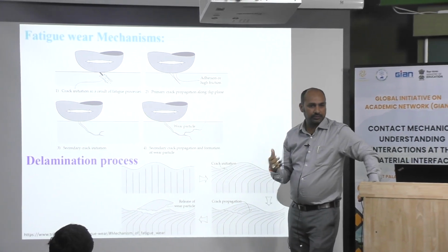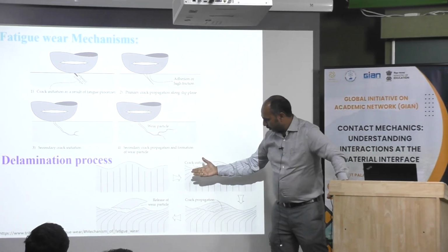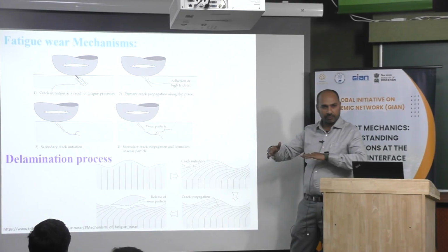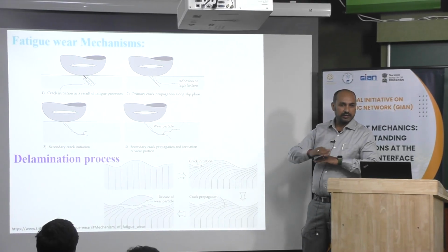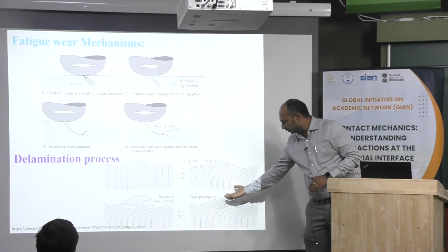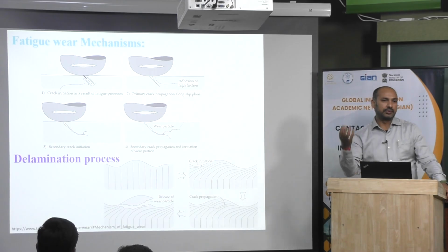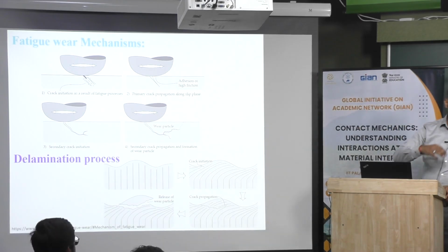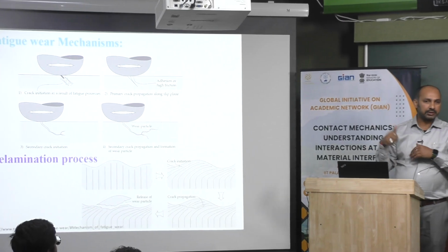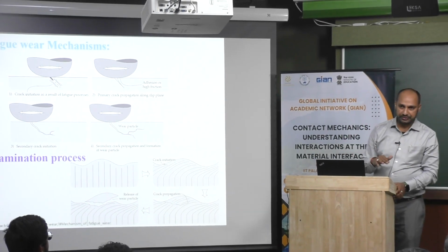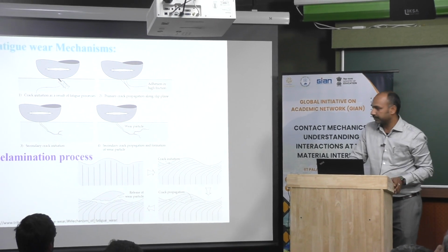Usually in the case of ceramics, this is considered as delamination. The complete surface gets deformed, some dislocation may occur, and then cracks occur, and this complete chunk will come out and be considered the fractured part. The fractured part will then be crushed under the compressive layer and form debris, which can be supportive as well as destructive. We'll see it one by one; it comes in both ways.